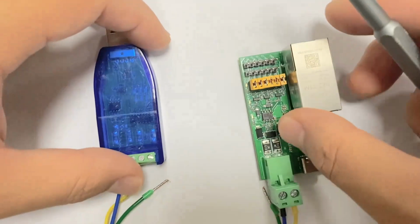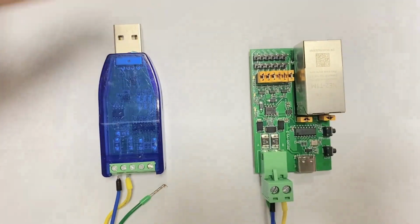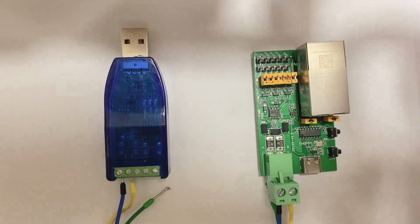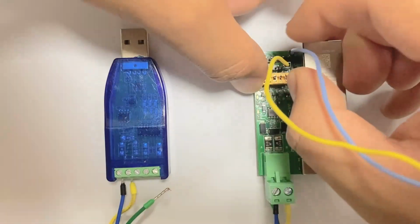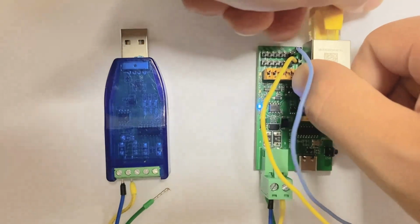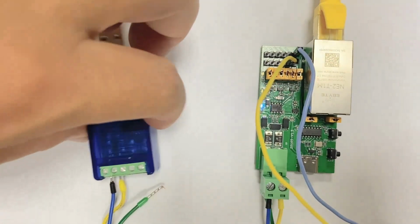Regarding module power supply, please refer to the product manual as different modules have different power requirements. When using RS485, power can be supplied via Type-C or directly through pin headers. In the demonstration, we will use pin headers for power. The method of connecting the network interface is the same as when using Type-C.